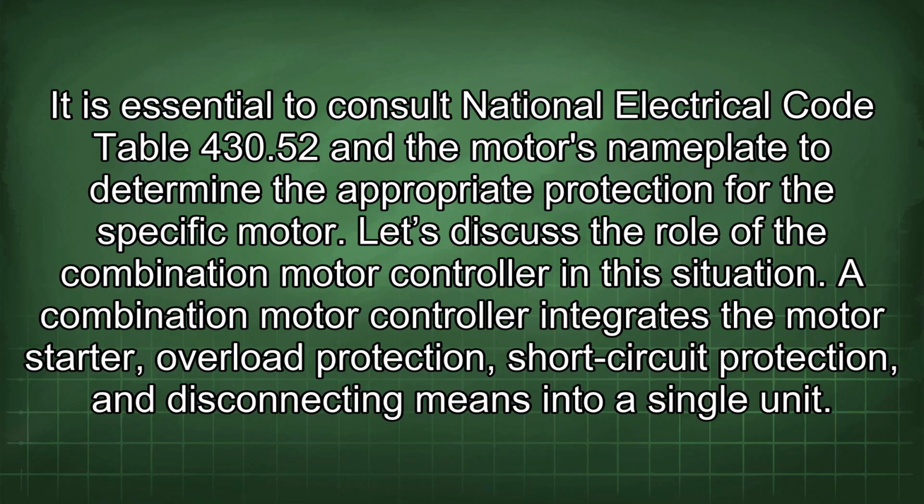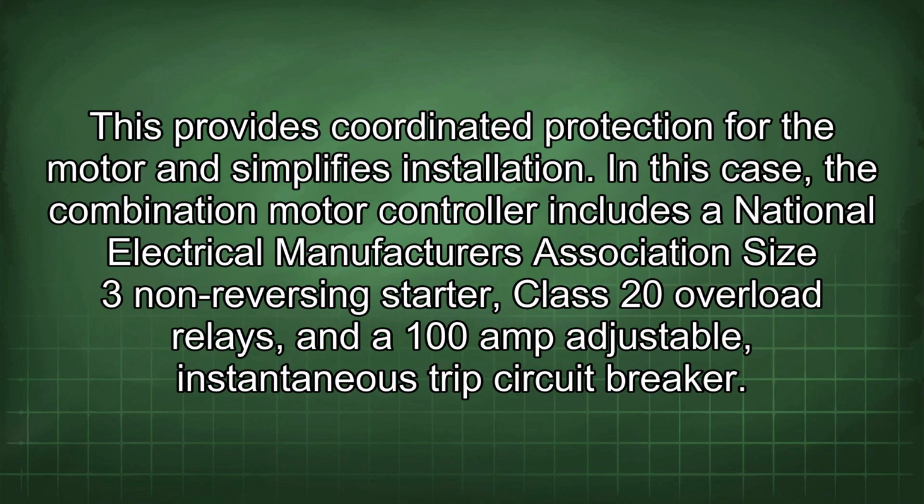Let's discuss the role of the combination motor controller in this situation. A combination motor controller integrates the motor starter, overload protection, short circuit protection, and disconnecting means into a single unit. This provides coordinated protection for the motor and simplifies installation. In this case, the combination motor controller includes a National Electrical Manufacturers Association Size 3 non-reversing starter, Class 20 overload relays, and a 100 amp adjustable, instantaneous trip circuit breaker.